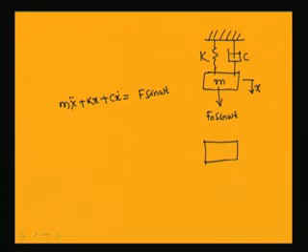So, when this body is moving downward with x, the spring will be stressed downward and so it will exert a force in upward direction, and that force is proportional to the displacement. That force is given by kx, and this damper also will be subjected to a force equal to c x dot, which is also opposite to the direction of motion.